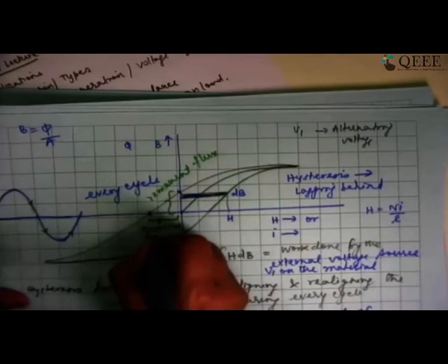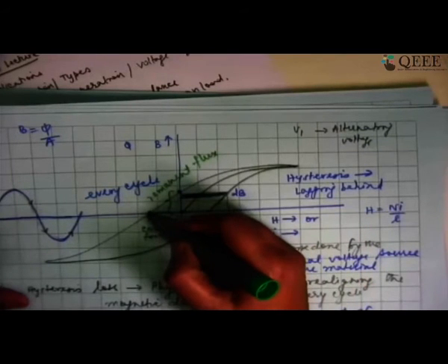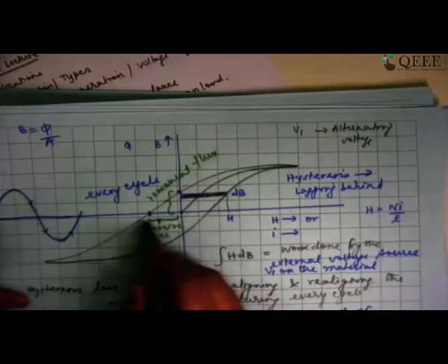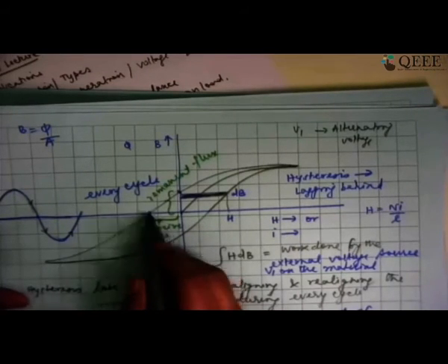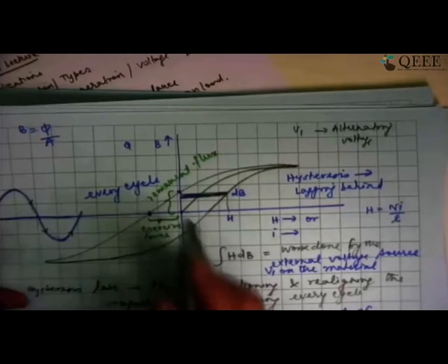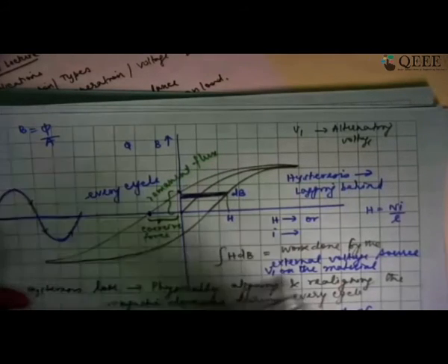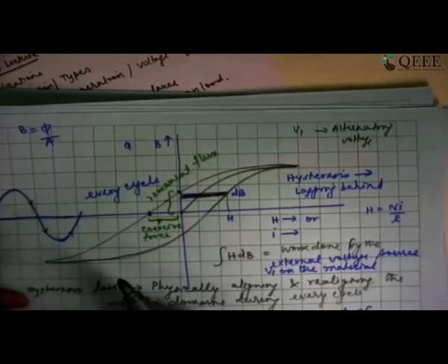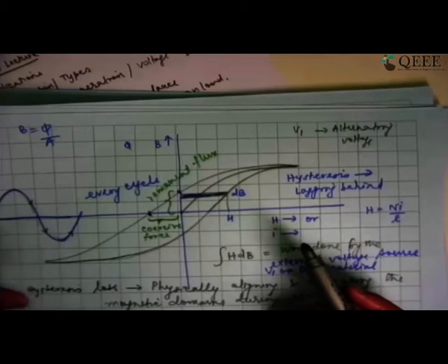I can say coercive force for any given flux density, but if I had gone up to the maximum flux density of the material and I am trying to bring it back to 0 flux density, then the current that I require to push through the magnetic core winding to bring the flux density back to 0, I call that coercivity. So the coercivity of the material refers to the current that I need to force through the winding wound around the core to bring back the flux density to 0. Have I answered your question?